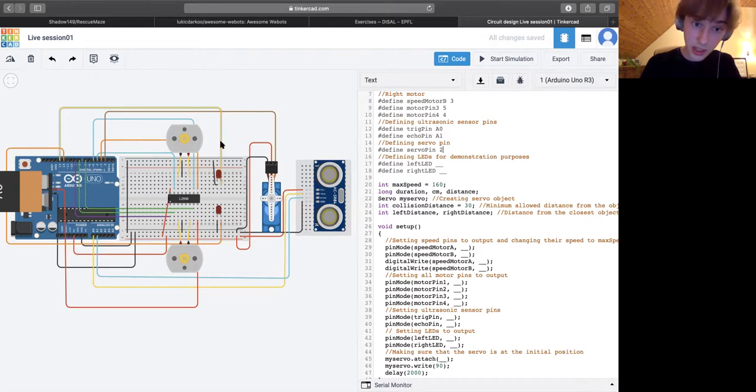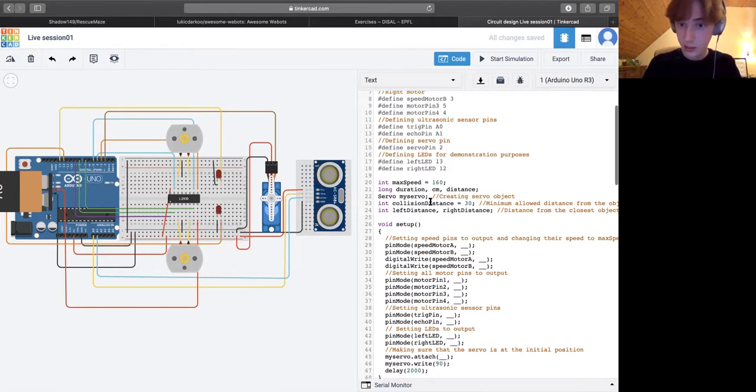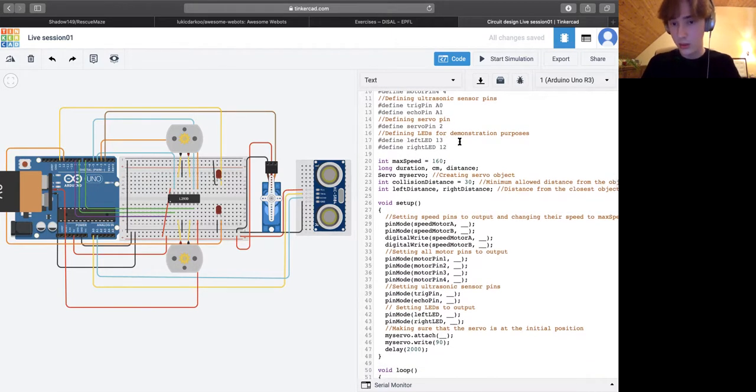And finally, we're going to finish off with the LEDs. For the left LED, which is this upper LED, we use digital pin 13, write that. And for the lower right LED, we use digital pin 12. As well, let's complete that. So it's all with the pin definitions.